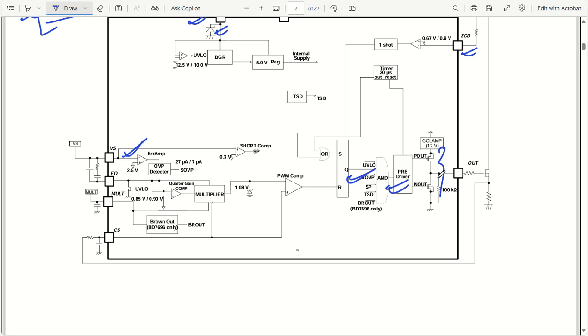Okay, and this push-pull MOSFET configuration is going to drive my external MOSFET. So let us say this is my N-channel MOSFET, which will have high current capacity, and here we will have one R sense, and this R sense is going to sense the current flowing through this MOSFET whenever it is on, and at that point this can be taken into my CS pin, which will be deciding the short circuit protection.